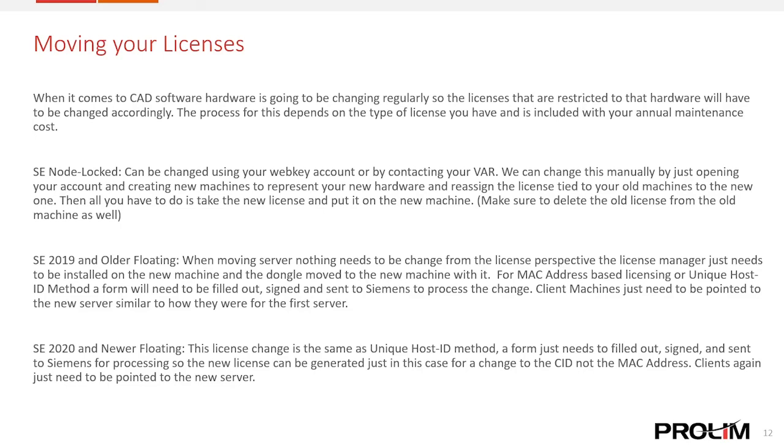So, for instance, if you're changing an NX node locked license that's hosted on a server, if you're changing the server out, like the server is being changed and the client machine is being changed, you would need to fill out that form to change the host name, the CID, and the MAC address. All three.